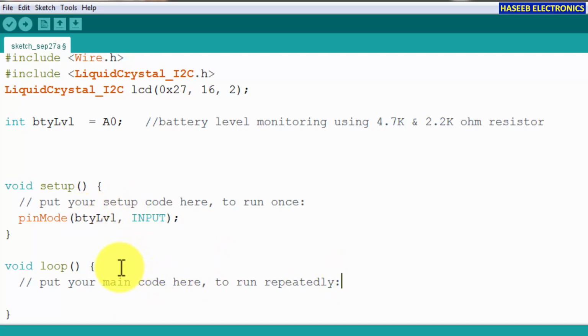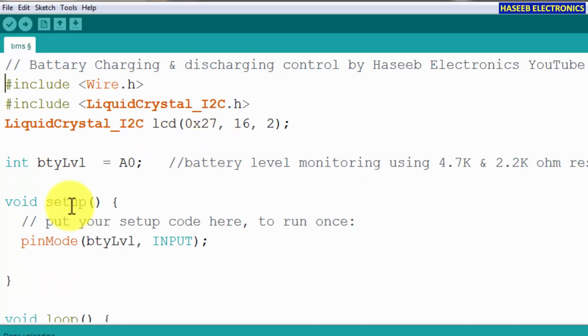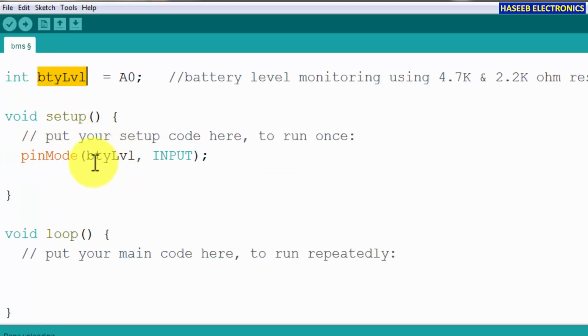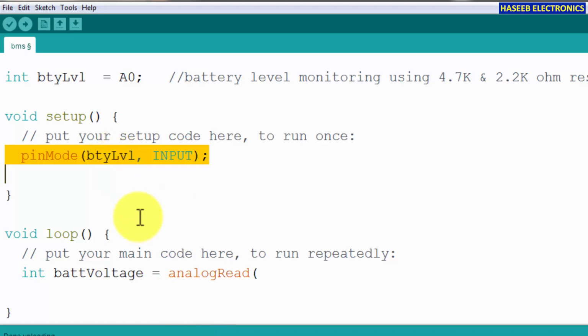Now how will we deal with this pin? We said that there is a pin, battery level. We will copy this name, and we defined the pin role of this pin, that is the battery level input pin. Now we want to measure the voltage. We will put an integer here, battery voltage. This is a name for our calculation. It is equal to analogRead of which pin? This pin, terminated. We set this buffer, this value, to equal the present value at the battery voltage.